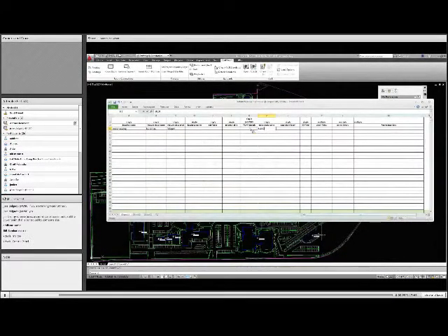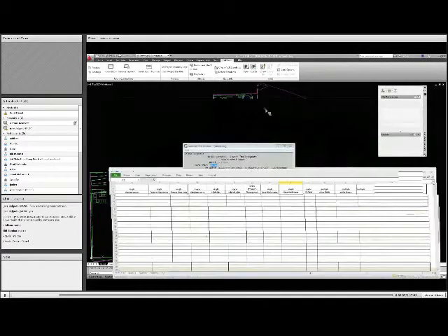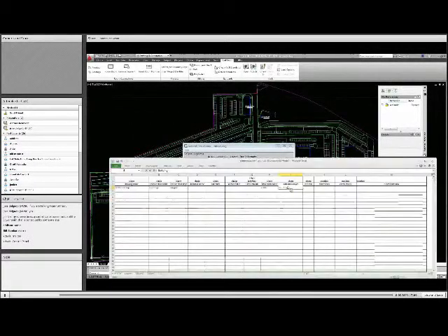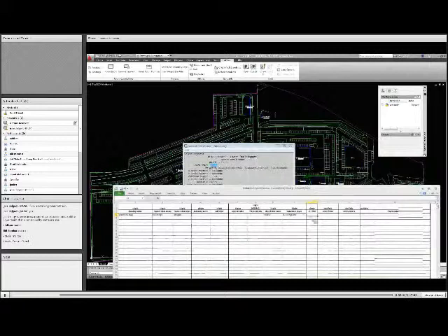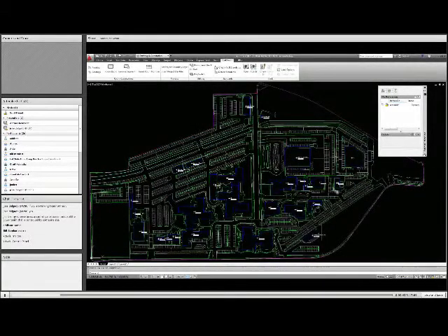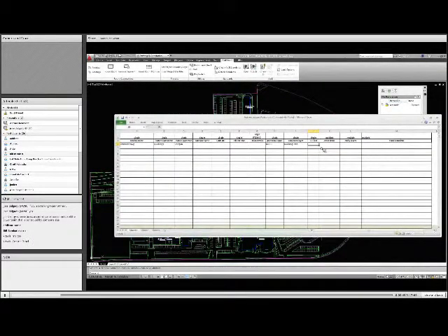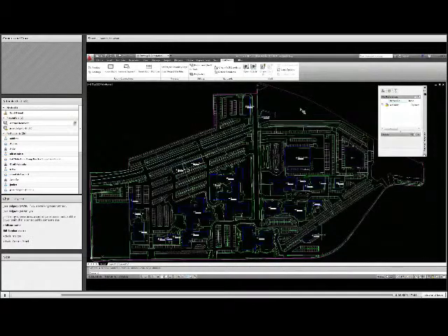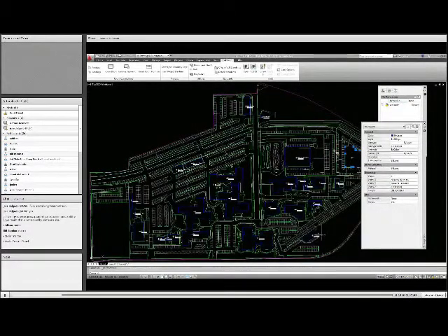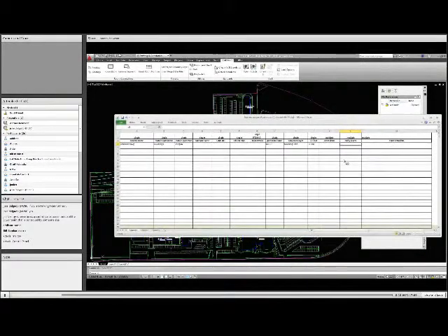I don't really have any other fields. And what is the layer of the polygons that I actually want? It's going to be the actual polygon boundaries, which is buildings. Put that in. Oops, caps lock. Before I do anything, I'm going to run my error checking command, which is just GIS check. Oh, close this first. This is one of the reasons why I'm trying to make this into XML. I'll copy that, close that, don't save it. This currently doesn't have anything in that file. Oh, because I had that open. Save that, close it.